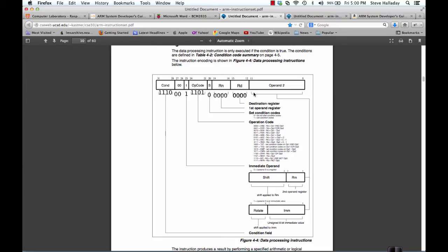Now I know that's a lot to try and understand, but stick with me here and I think it'll start to make sense. So the first thing that we need to do is load into register 0 a value of 0x20000000. Okay, and here's how we do that. We have to look at how this is encoded here. What this means is we take this rotation piece here, which is 4 bits, we multiply this value by 2, and then we use the result of that to rotate this IMM value that many places to the right.